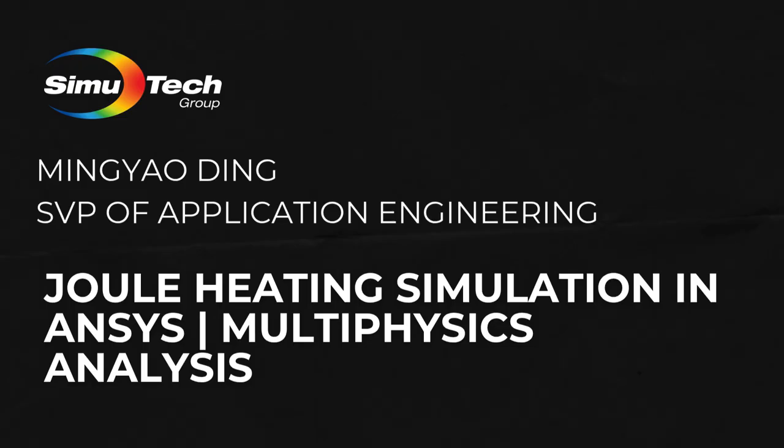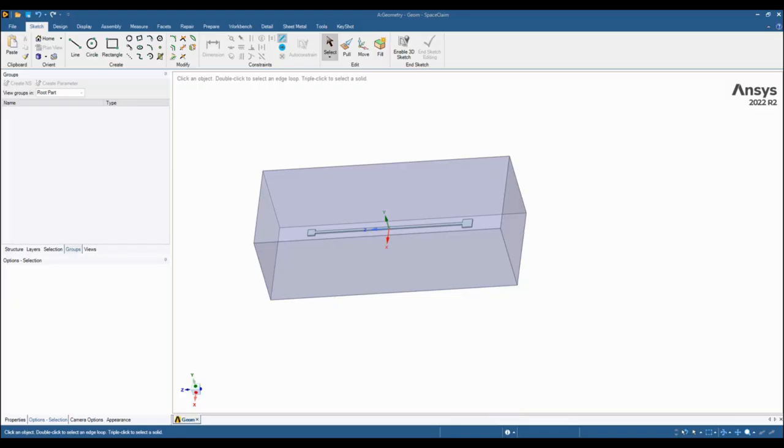Hi, this is Mingyao. I'll be looking at how we set up Joule heating simulations in Ansys Workbench. There are a number of different packages that can do this. I'll be starting with Mechanical, Ansys CFD, and then Icepak. Joule heating is the condition where running a current through a conductor generates heat. So it's a multiphysics problem that requires us to model both electrical conduction and heat transfer, and for fluid dynamics, thermal convection into fluid.